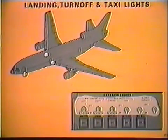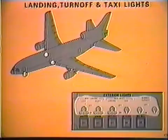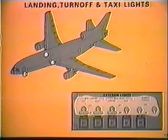1 fixed position landing light is installed in the leading edge of each wing fuselage fillet. There are 2 fixed position lights on the nose gear that serve as high-intensity landing lights and lower-intensity taxi lights. Runway turn-off lights for side vision are also installed in the wing fuselage fillet directly above the landing lights.